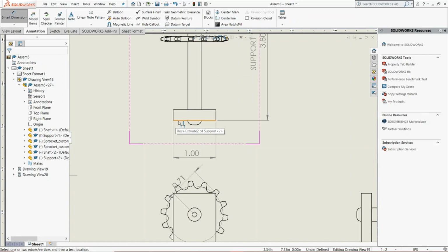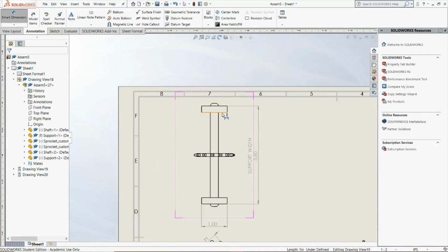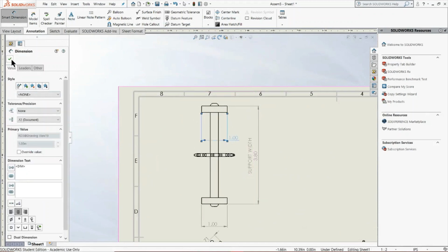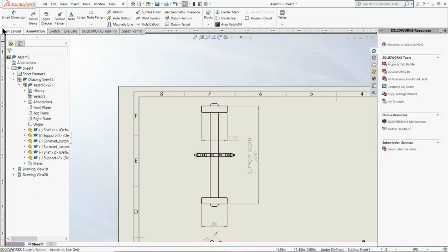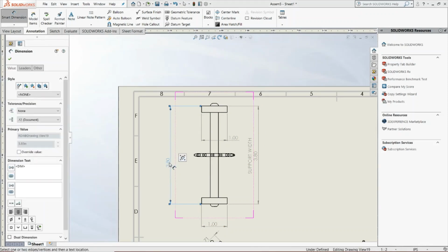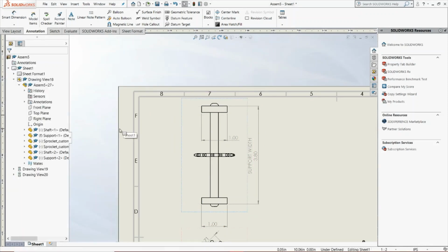Essentially what you do is you take any horizontal length. I've already done this, so this is a bit redundant, but you take any horizontal length and you put a dimension in there. Same thing for the vertical dimension. It's just we're dealing with vertical lengths as well. I'm going to get rid of both of these because we've already got these 2 dimensions located.